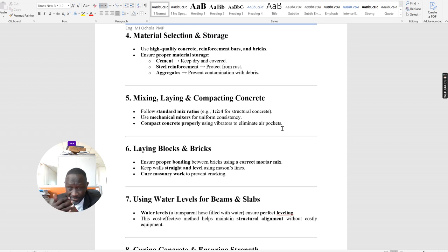You find a design report has reference to concrete grade, reinforcement strength used, and then I told you for bricks, sometimes the minimum strength of bricks is also indicated. Mortar type, mortar strength, all indicated.